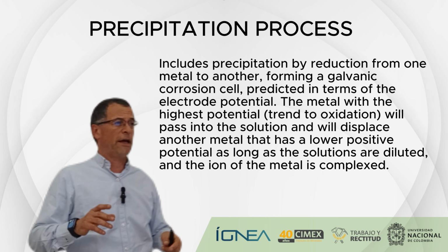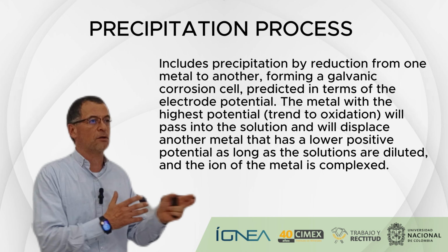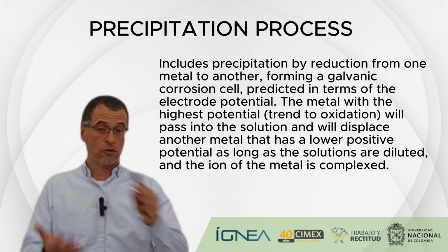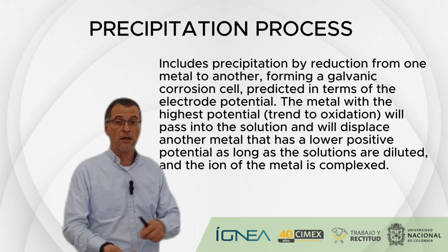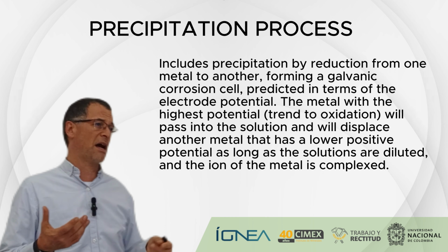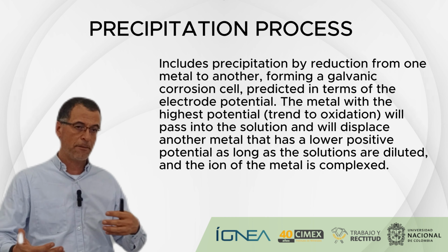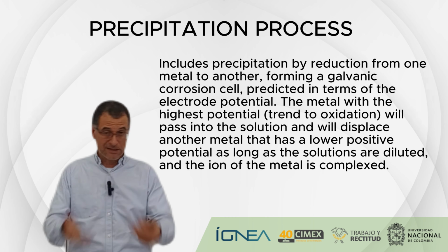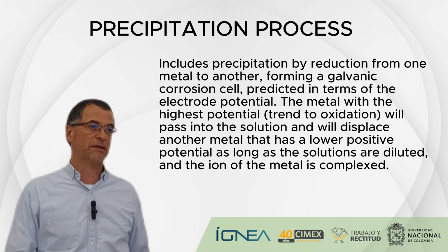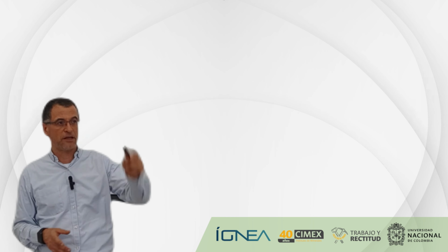When you are going to do the precipitation, you have to define what methods you are going to use, because you could use another metal in order to precipitate your metal of interest. The name is cementation. Or you could use a special electrostatic processing, using electricity, or use another solution in order to precipitate the material you want to work. The more common method is cementation.